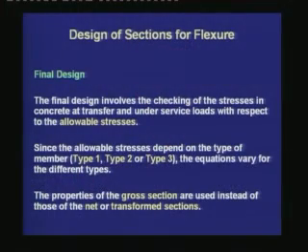Now, the final design involves the checking of the stresses in the concrete at transfer and service loads with respect to the allowable stresses. This is a very important step of the final design, that we need to check the stresses in the concrete. Since the allowable stresses depend on the type of member, type 1, type 2 or type 3, the equations vary for the different types.